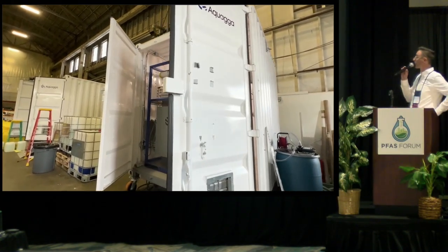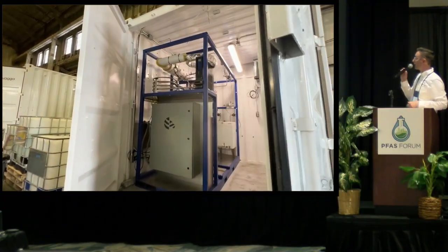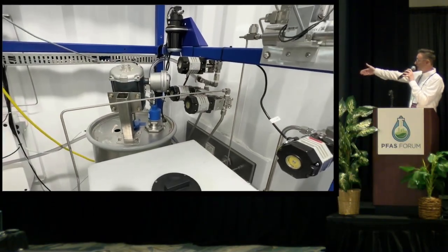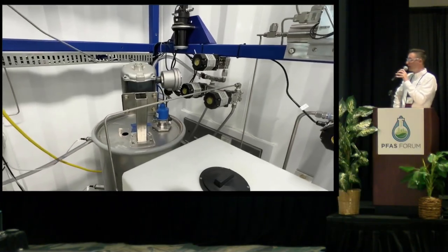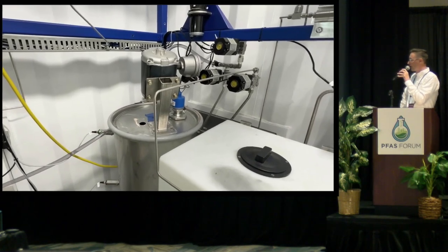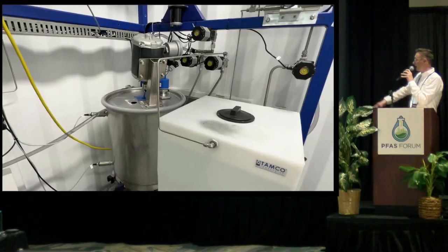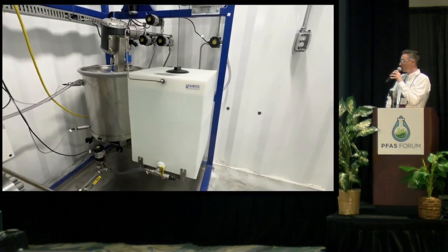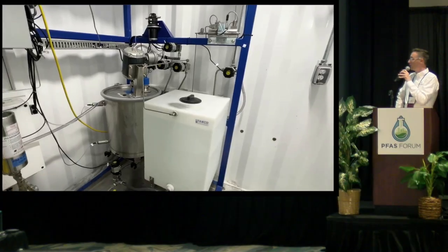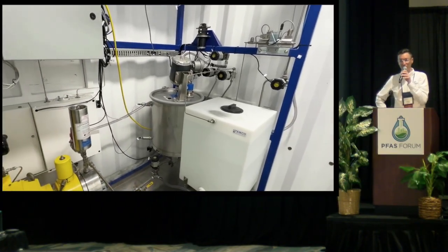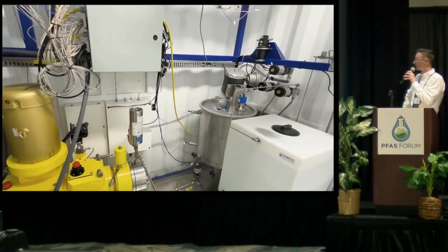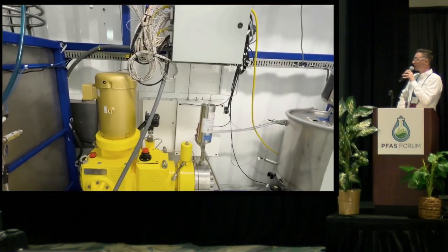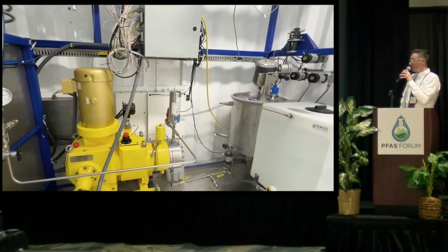It's just me. So you open the doors, and there's the HALT system in there. It takes up about half the container. Those are the influent connections here. The feedstock that's been amended with alkaline goes into that silver tank there. That's just a holding tank, leveling tank for the pump. We get fresh water. That's for system heat up and rinsing of our system. All of that's controlled by valves. Goes into the pipes. And then it enters the high pressure system through an industrial diaphragm pump. Quite a big pump in there, you can see. Again, we're pumping it at about 3,000 PSI into the high pressure system. It then goes up through the pipes.